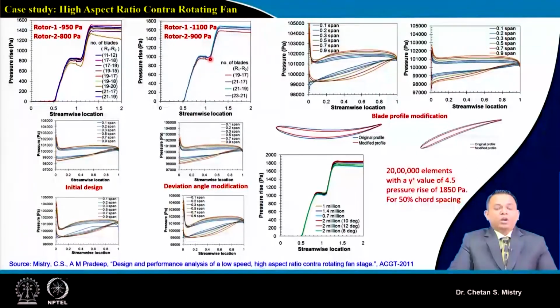When we did this, we initially fixed our number of blades based on a number of iterations. Then we need to check, for this particular aerodynamic loading, whether this number of blades comes out as per requirement or not. Let me tell you, in this case our blades are high aspect ratio blades. So the height of the blade is large and the chord is smaller.